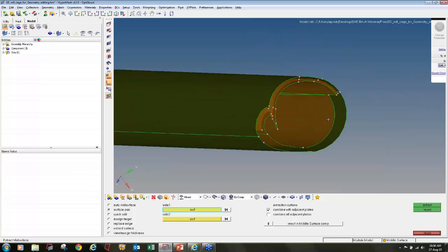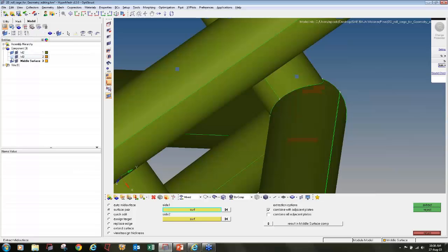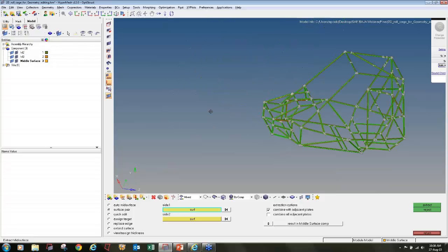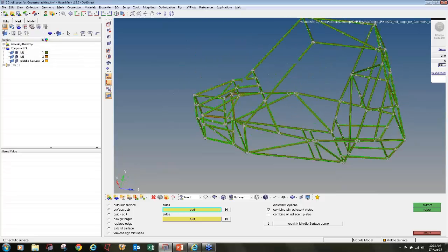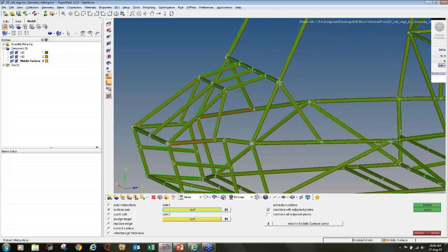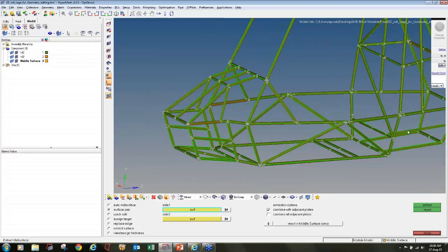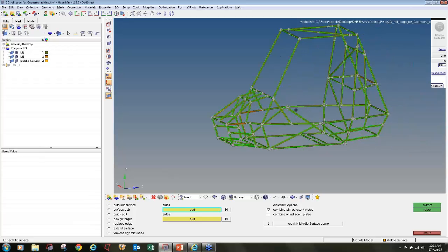Another thing generally people don't do is, in the software they just bring this file, or they can have a direct mid surface geometry from the CAD. They bring the file, mesh it, apply the force, constraint and solve it. But they don't check whether all the pipes are properly connected or not. If all the pipes are not properly connected, then the results may vary.